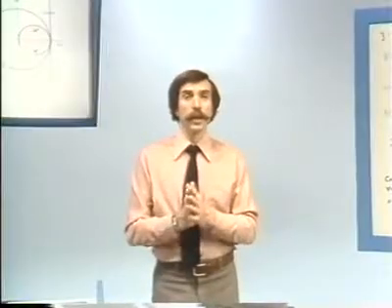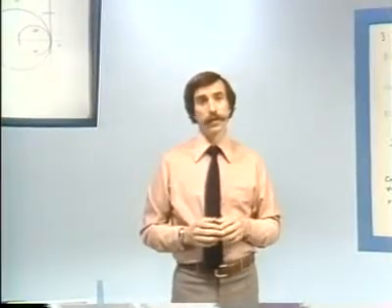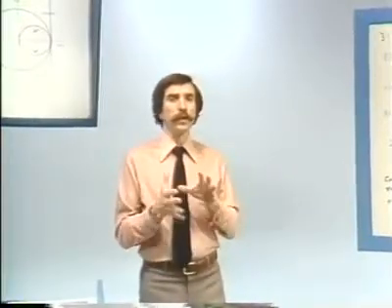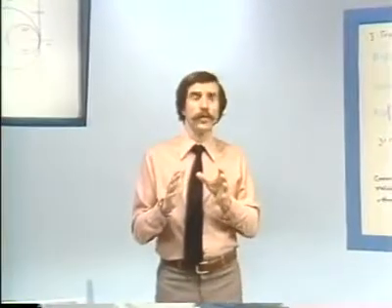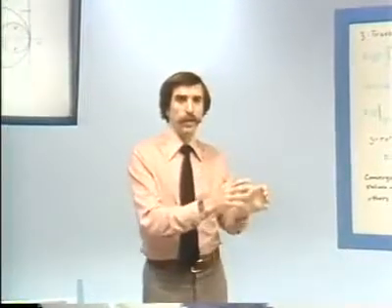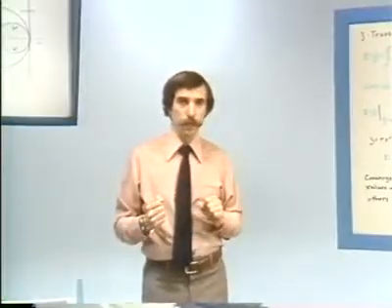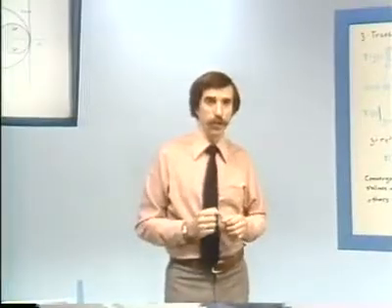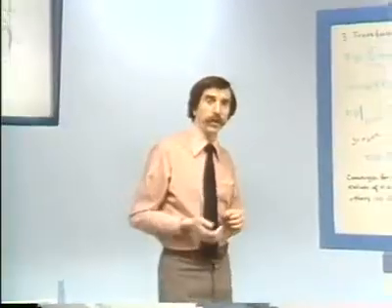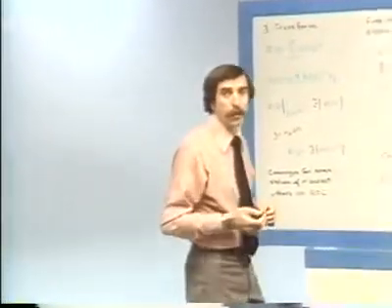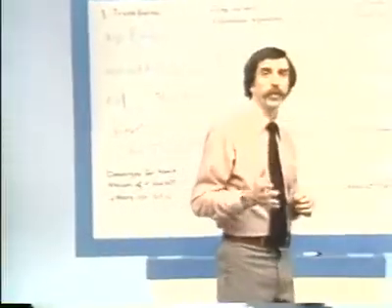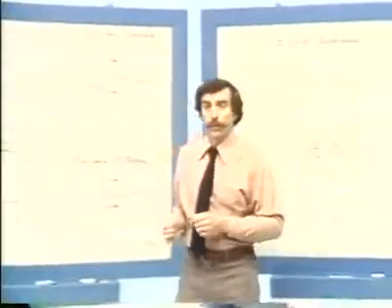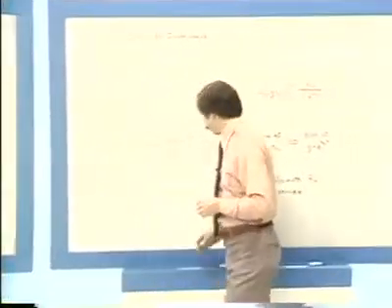The next method that I'd like to talk about is a method that in fact is very commonly used, and it's a very important, useful method, which can be motivated by thinking along the lines of mapping the continuous time filter to a discrete time filter in such a way that the shape of the impulse response is preserved, and in fact more specifically so that the discrete time impulse response corresponds to samples of the continuous time impulse response. And this is a method that's referred to as impulse invariance.